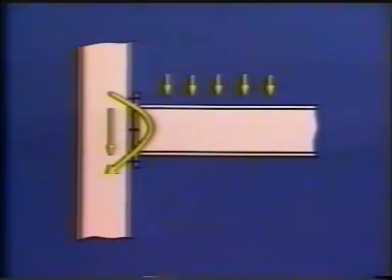Because the primary role of the column is to carry the vertical loading to the foundations, the governing force in the section is usually axial compression. This is often accompanied by moments transmitted from the beams, produced by beam bending.